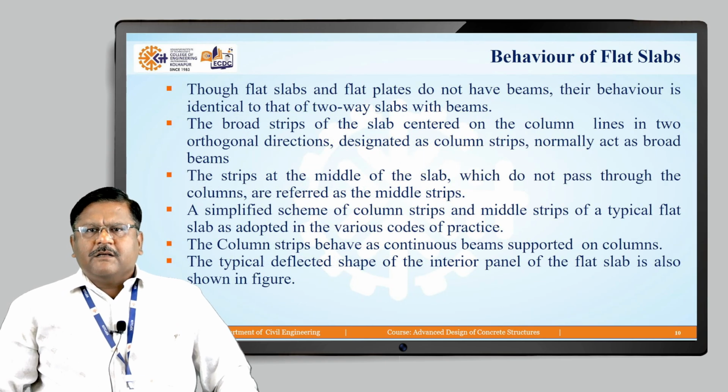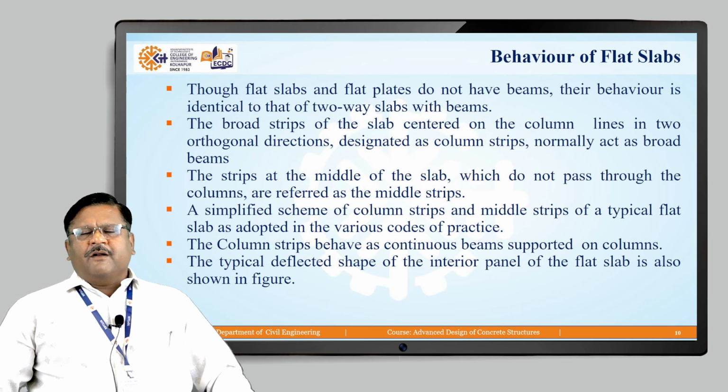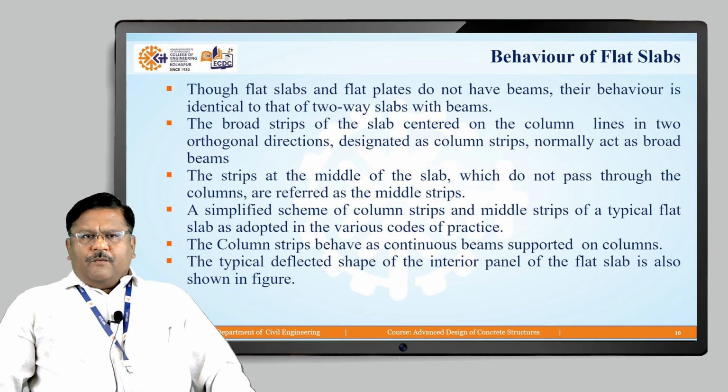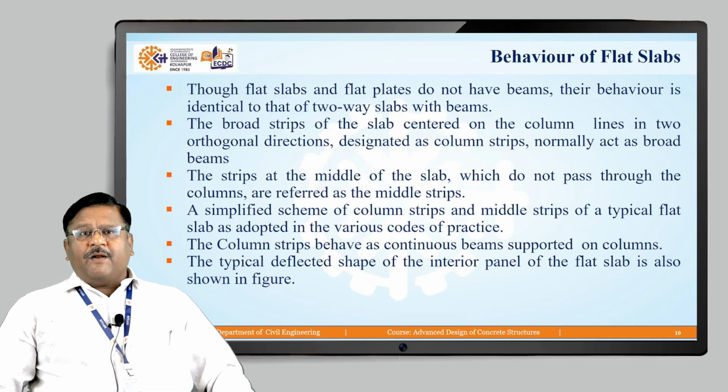Next, behavior of flat slab. Up till now we discussed the advantages, disadvantages, and the major terms used during the design. Now what is the behavior of flat slab? Flat slabs or flat plates do not have beams. Their behavior is identical to that of two-way slab with beams.